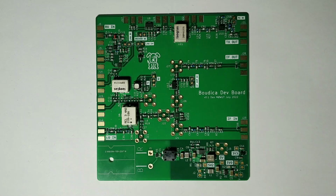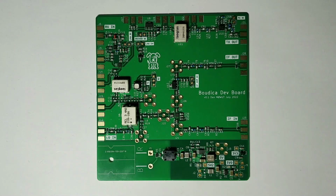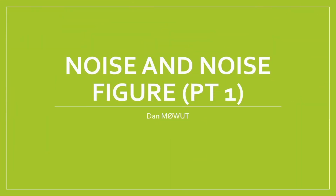Hi, so I'm getting ready to have a look at this 70cm transverter I designed, and I thought before we did it'd be a good idea to actually walk through some of the more complicated RF measurements we're going to do on it, how we make them, why we care, and how they affect the performance of our circuit. And I thought an excellent place to start with that would be having a look at noise and noise figure, because this is going to be one of the key parameters of the first block we're going to analyse.